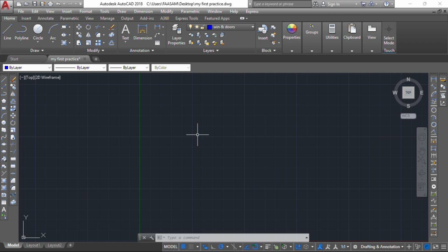And for internal doors, maybe your room door or your kitchen door, they are always 900. And toilet doors are always 750. That's for the width. Now for the height of any of your doors, be it the entrance door, the kitchen door, or the internal doors, it is always 2.1. That's the height for any of your doors.